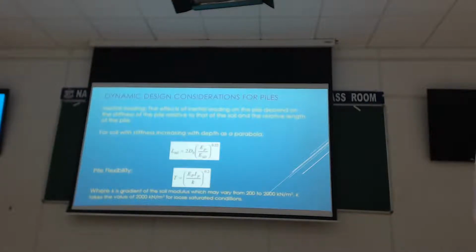It hurts me to say Young's modulus of soil, because although there are books written on this, Young's modulus of soil does not make any sense. This is part of the problem: all this nomenclature is coming from using elastic systems. And I've been showing time and time again these things are not elastic. The material behavior is not elastic. However, let's learn what other people are saying, and then we can go and cut them out.